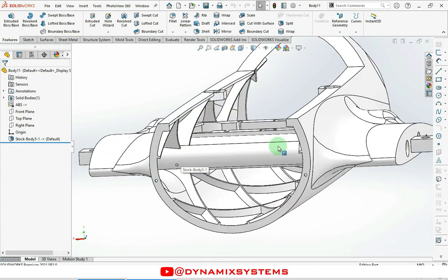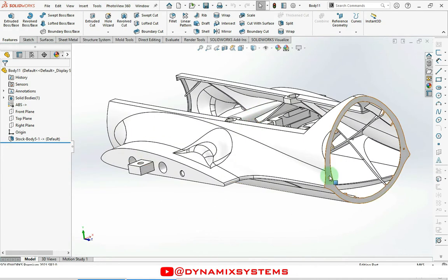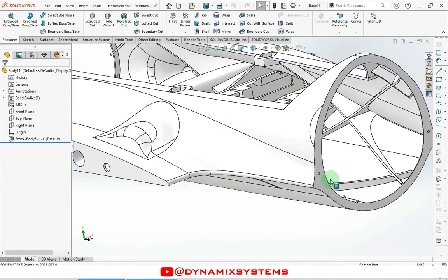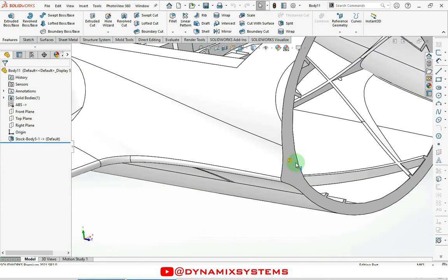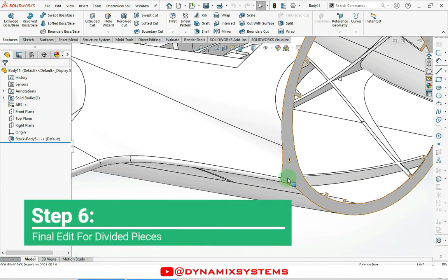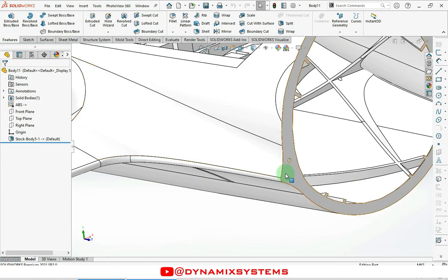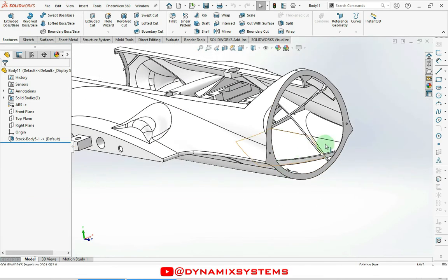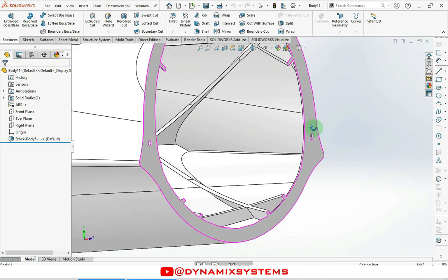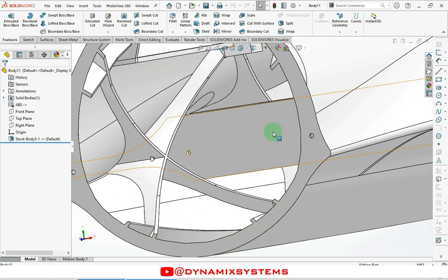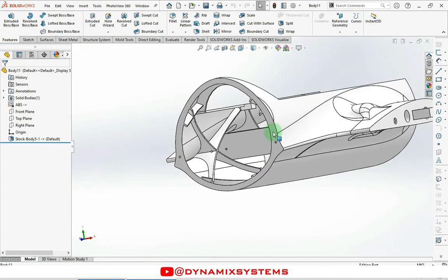So we have these flanges to create the bond and these holes for the adjustment. And actually we can use some wood stick or carbon fiber rods with the 1 millimeter of thickness to align them and even make the bond stronger.